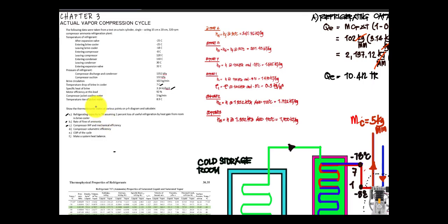Now going back to the data which is given in the problem, we have here the temperature rise of the jacket water, which is 8.9 degrees Celsius. So we can use this to determine the heat being released. We have the change in temperature, and we also have the mass flow rate for the given jacket water circulating our compressor.